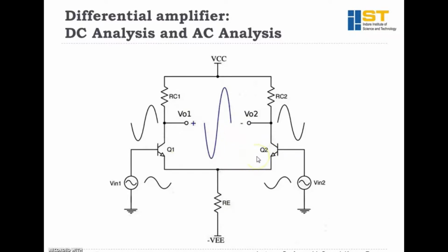So in this regard, we can have four different types of differential amplifier, and to understand that, we need to understand what is a balanced output. Balanced output means that if you are taking output between these two terminals, not between this and ground and not between this and ground, so that is known as balanced output. And if you are taking output between this and ground, and this is not used, then this will be known as unbalanced output. So we can differentiate differential amplifier in four different categories, like dual input balanced output, single input balanced output, dual input unbalanced output, like this.